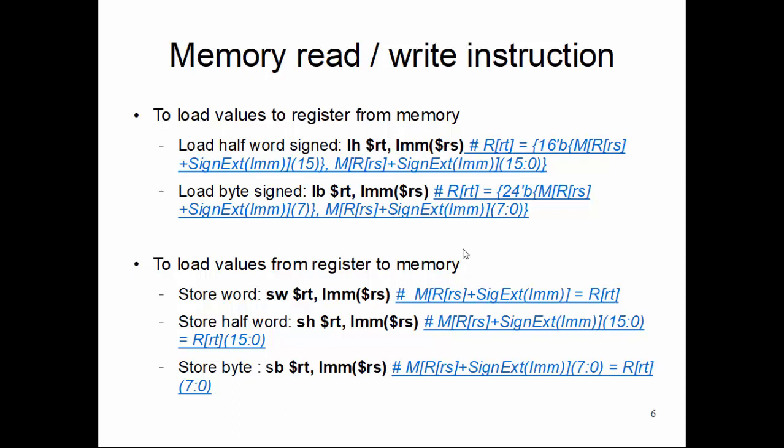But anything below that, like half word or byte, has a signed notion, right? We cannot mess up a value if we want to treat it as a signed value. Remember, unsigned and signed, the same bit pattern we can actually treat as signed or unsigned, but it really depends on what usage you are doing.